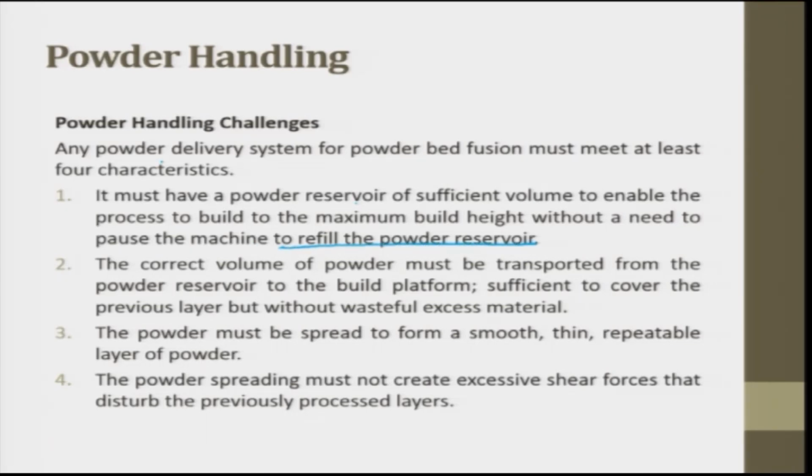So this is one thing which you have in between, you cannot stop. If you stop it, refill it and restart it, then there will be a delamination. The correct volume of the powder must be transported from the powder reservoir to the build platform, sufficient to cover the previous layer but without wasteful excess material. The powder must be spread to form a smooth, thin, repeatable layer of powder. Powder spreading must not create excessive shear force that disturbs the previously processed layer.